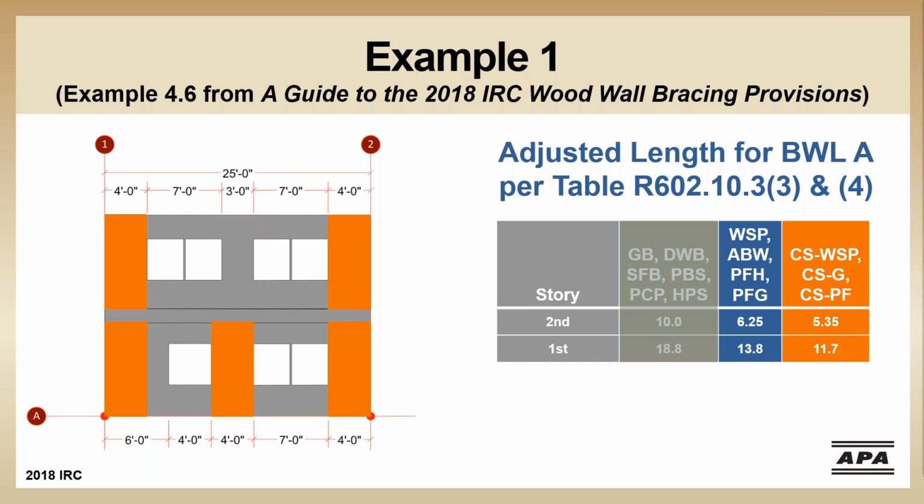I've only highlighted here the wall areas that I'm counting as braced wall panels. Obviously, because this orange column is all continuous sheathing methods, the entire wall needs to be sheathed, including above and below the openings and any gable ends. But these would be the qualifying braced wall panels. Notice neither layout includes the braced wall panel overhanging an opening, so we're good on braced wall line A.